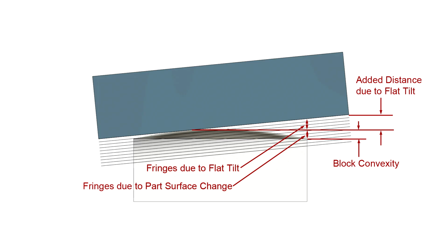Just for a reality check, here's a real fringe pattern of a gauge block that's roughly 40 microinches convex, not a smooth contour like the model, but in the ballpark. I'm just tweaking the flat angle to see the difference in fringe patterns. Here the flat is fairly parallel to the surface. It's very touchy, and as I tilt in various directions, the pattern changes. It does appear that the surface is high in the central region.